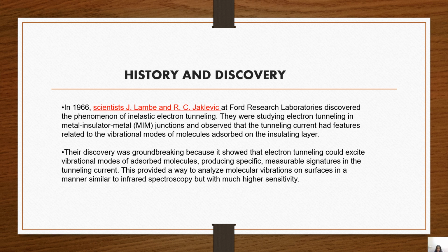IETS can probe single molecular junctions and nanostructures with remarkable sensitivity, making it a valuable tool for investigating phenomena like electron-phonon coupling. Also, its high resolution and non-destructive nature make it suitable for characterizing complex systems without altering their structure.